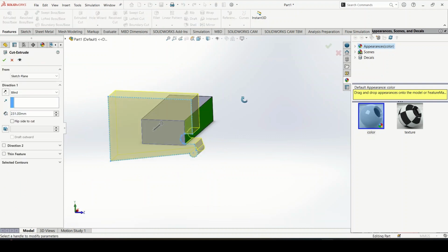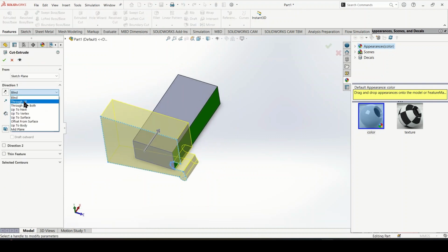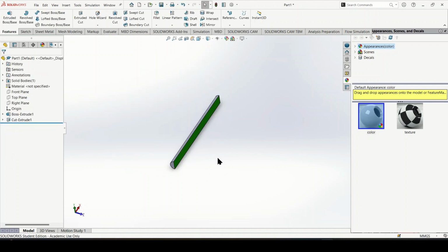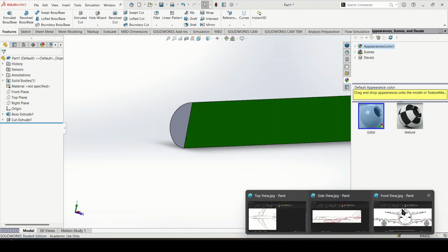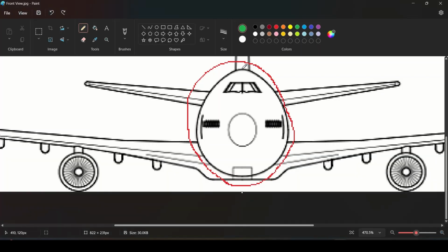And so now from this we can make an extruded cut and through all checkmark. And as you can see here, we still have the green space. If you wanted to, you could also just kind of try and do the spline curve on your own after creating these three broad points. Just sort of eyeballing it, and then we'll reflect over in the next step so you won't have to repeat the exact dimensions on another step.